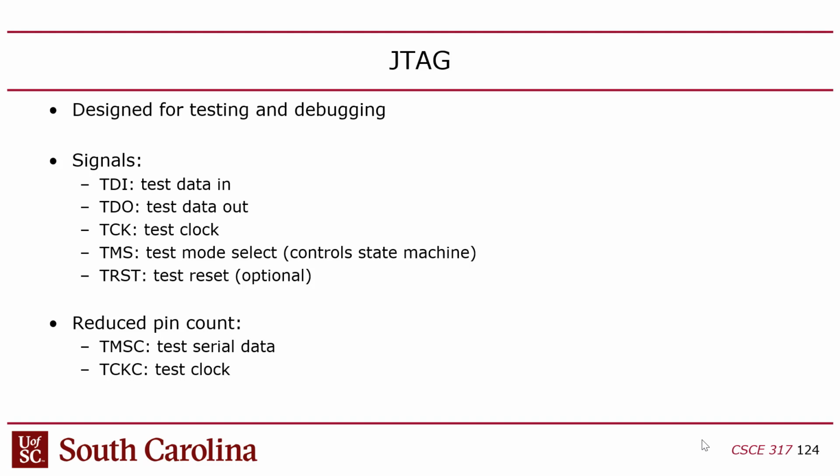So that's what we're dealing with. But JTAG has 4 wires minimally. There's some optional wires. But the thing that's neat about JTAG is that you create a chain with it. So it's very similar to using SPI in daisy chain mode.